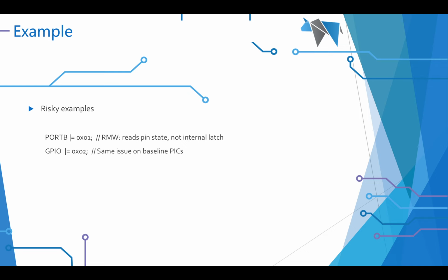And because it reads it in and then applies the rule of number one to it as an OR statement, it will just break it and you'll get bad results. And the bits will just move around. This is a very well-known problem. It is not an issue with the GCBASIC compiler, and it's the same on GPIO on some of the other chips, and we'll look into that in the baseline chips.